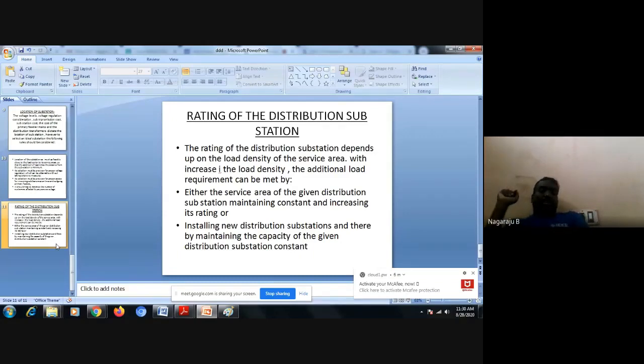And x1, x2, x3, up to xn are the distances corresponding to the reference point. I have taken one reference point, and I need to find the center of gravity. Center of gravity is equal to m1x1 plus m2x2 plus m3x3 and so on up to mnxn, divided by m1 plus m2 plus so on up to mn. This is how the center of gravity is found.